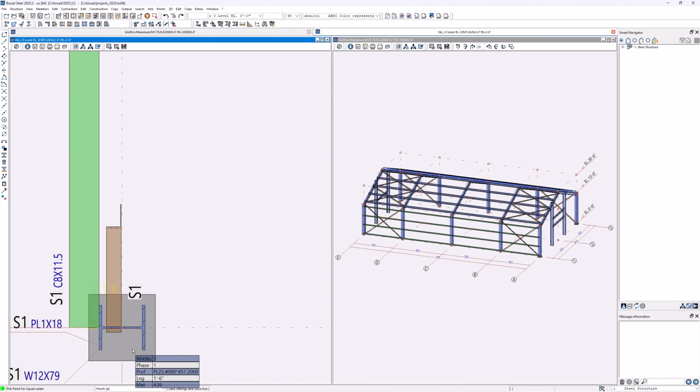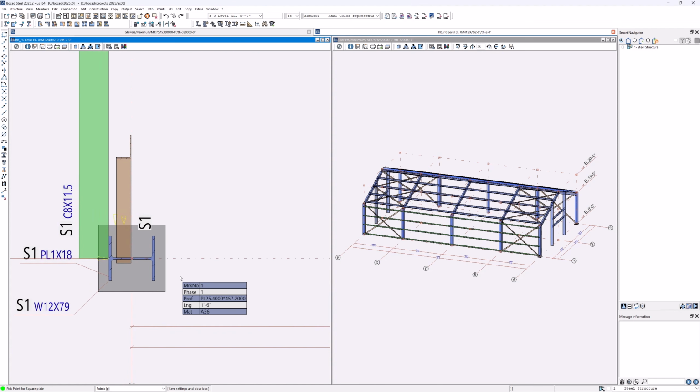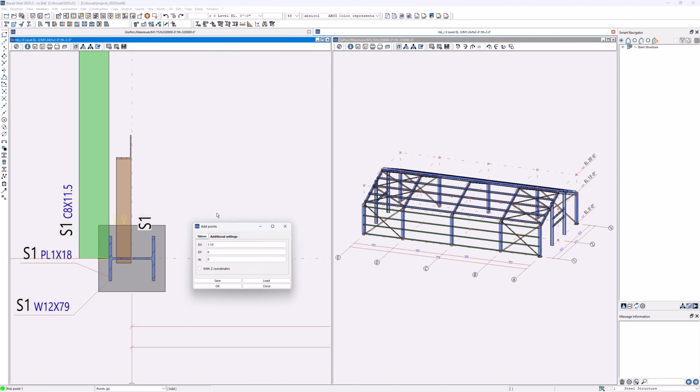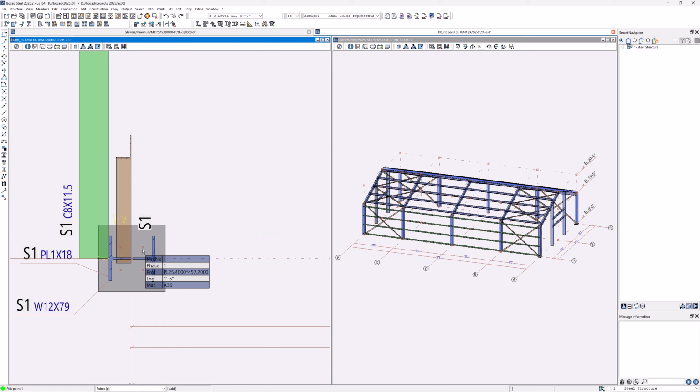So if I were to create any holes or anchors into this base plate, I might need a couple of coordinates first. Coordinates that could be used through points or placed through points. Add is a typical one, where I would say we're going 3 inches one way, from there -6. So 3 inches one way, -6. Copy that value in Y, and from center, we're indeed then going in all directions. So at least then I have a couple of references to create a connection.